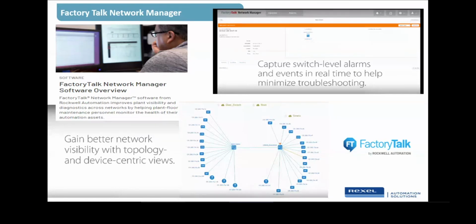We found that FactoryTalk Network Manager is one of our first recommendations after an assessment to increase visibility and diagnostics across the machine level network. OT professionals were just lacking the visibility needed or the comfort required to actually configure the managed switches on their floor. Our network engineers do work on site with you to properly deploy this offering from Rockwell Automation.